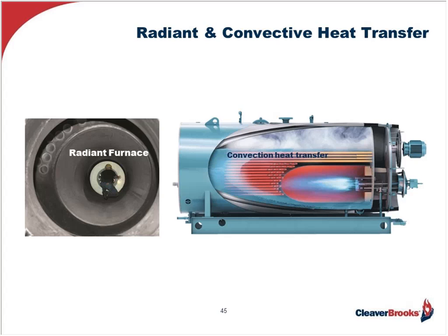So the design engineer calculates the required nozzle size considering the operating pressure and mass flow of the steam, and this is to deliver no more than 10 feet per second velocity across the surface of the water in the boiler, and an exit velocity not exceeding 5,000 feet per minute out the steam nozzle. So maintaining these velocities should keep the steam as dry as possible and avoiding the carryover problem I just mentioned.